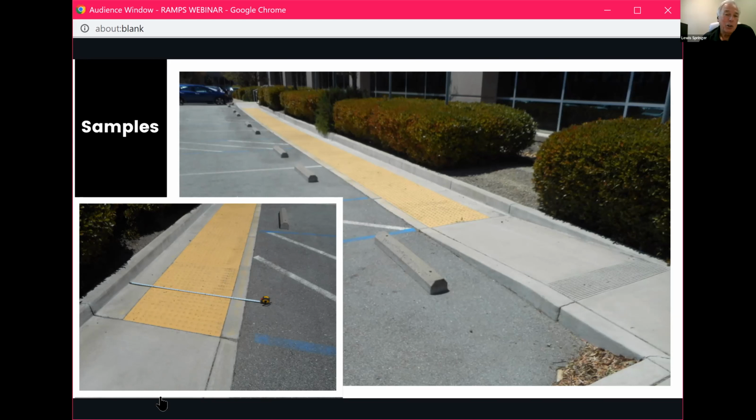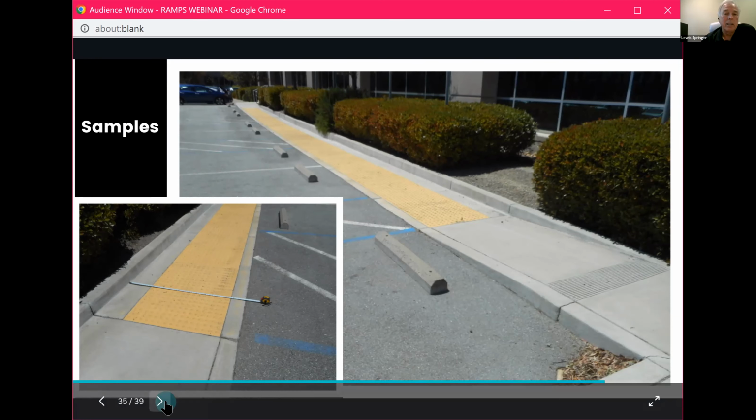So we're going to look at this one as one curb ramp, one parallel curb ramp with a landing. So the landing is designed so that it's a blended transition in between the walkway and the vehicular area. The only difference now is that this would be required to have 3 feet of concrete on the backside so that you can have a walking space free and independent of the detectable warning. Okay, next slide.